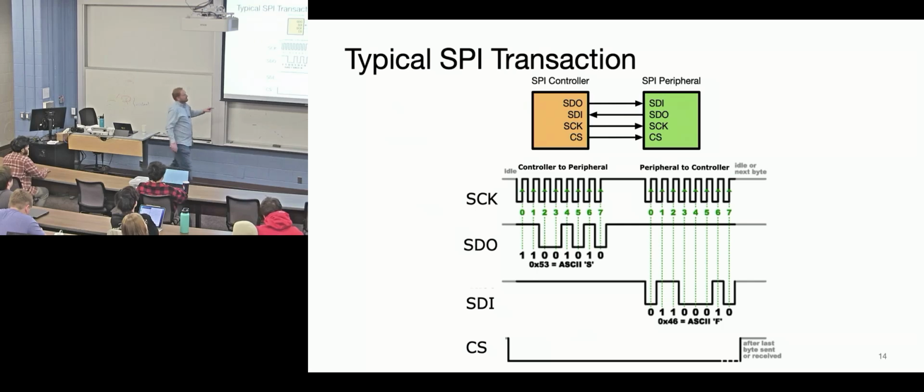Here you don't necessarily have to bring the chip select down or back up. You can if you want. It depends on what the peripheral spec is, but you could just keep it low the whole time to indicate that you're going to keep focus on that particular peripheral.